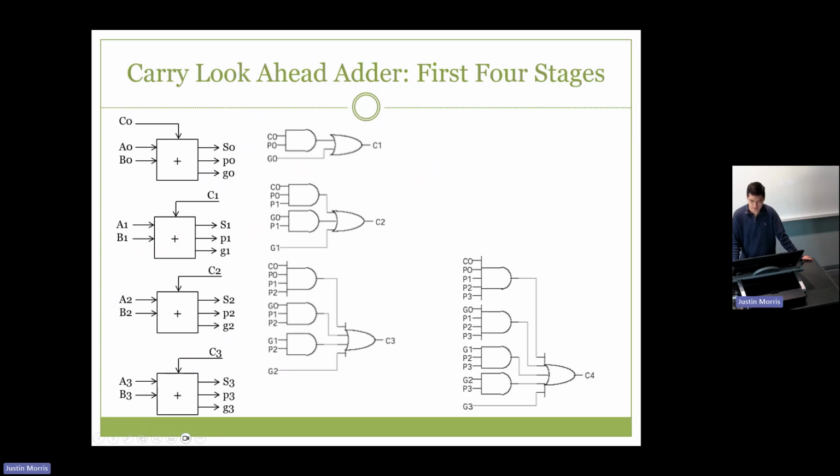Okay, because I go through 1, 2, and well, let's do the C3 because this one is just carry out. So I go 1, 2, and then inside this adder I go through 2 more. And then it's the same for C2, 1, 2, and then 2 more. So I'm no longer going through 8. I am at maximum 4 levels with the carry look ahead.